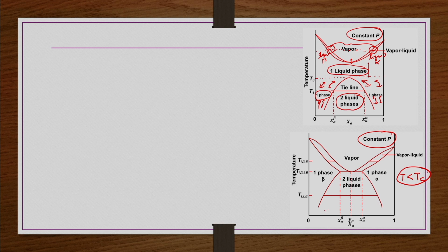So, before there is a LLE, obviously we can see here at this temperature TLLE, within this envelope we have LLE of the system, and then before this we usually have this kind of system. So, before it reaches the upper consolute temperature, the pressure is reduced such a way that the more volatile component is vaporized and then VLE is also started, and then that VLE behavior and LLE behavior are coinciding with each other, so that we can have this kind of picture here.